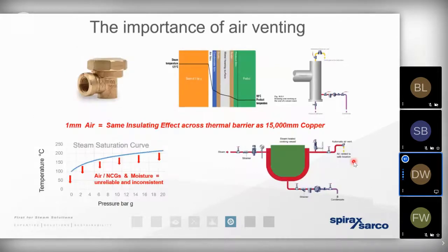And we also mentioned that we want the steam to be kept as free of air and other non-condensable gases as we can. So we treat the water in the hot well with chemicals to purge off an excess of air and non-condensables. But the purpose at that point is to protect the boiler from corrosion.